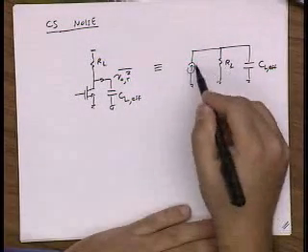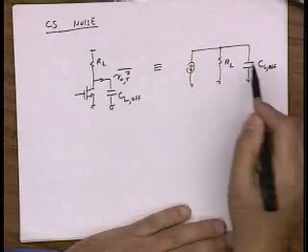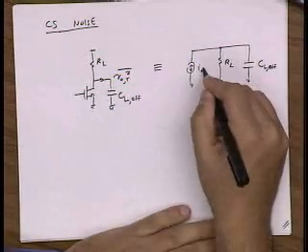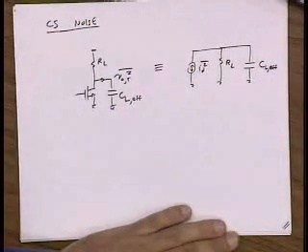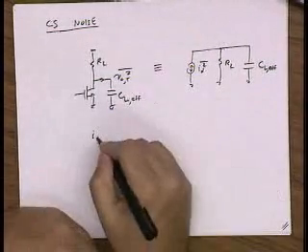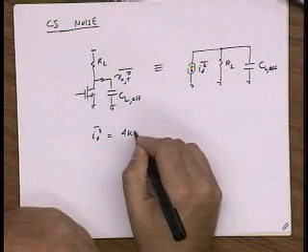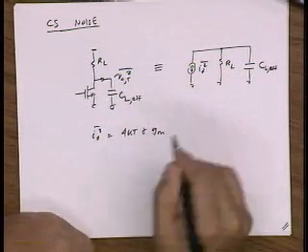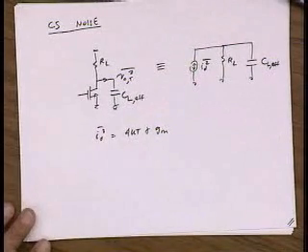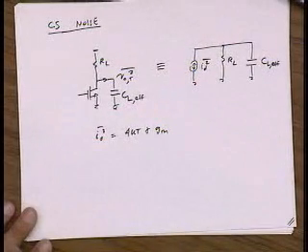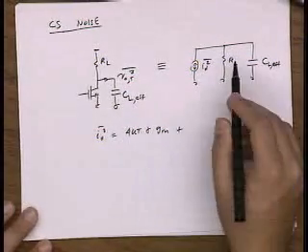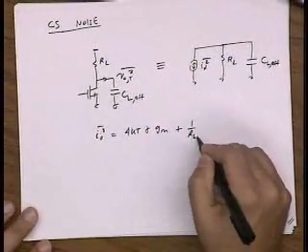And then what's the noise that's actually being integrated on this capacitor? Well, the noise is the noise of this transistor's drain current, with variance equal to 4kT gamma times gm. Now, what's interesting about this problem, let's also include the noise of this resistor, so 1 over RL.